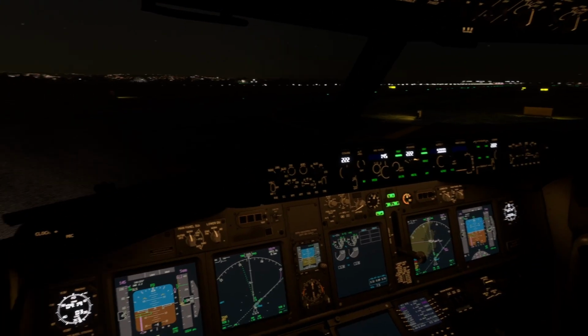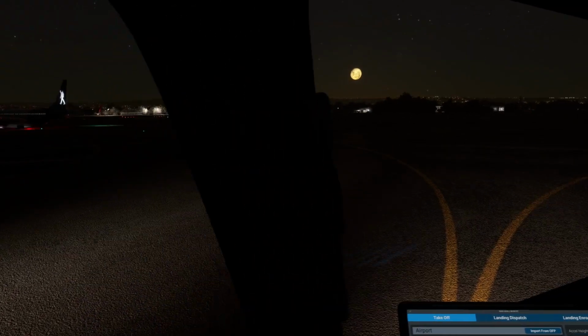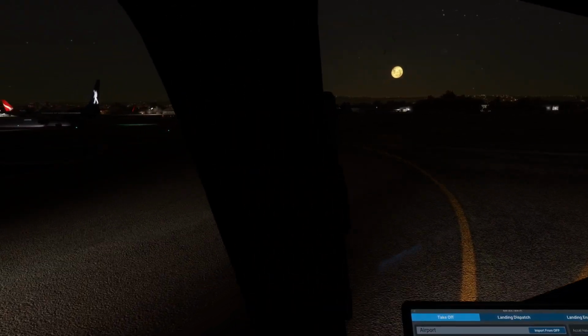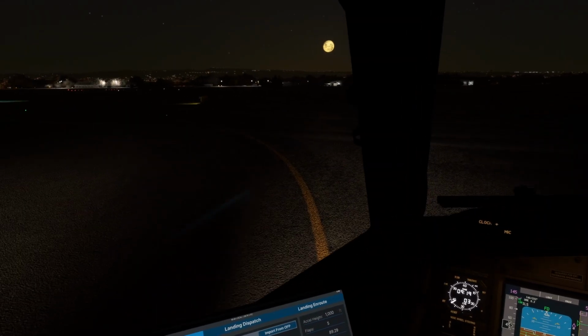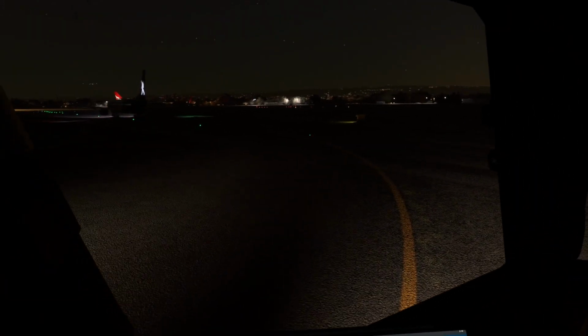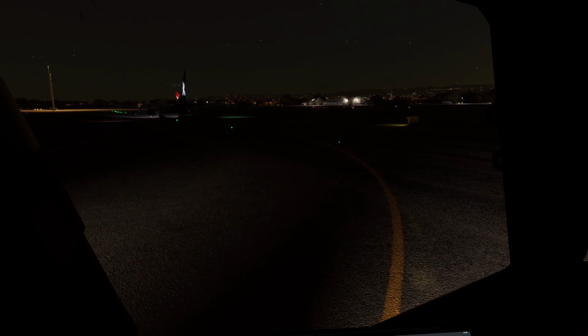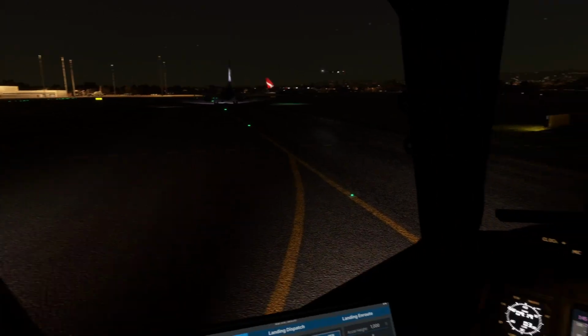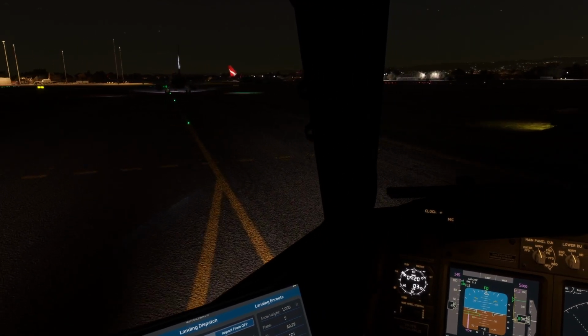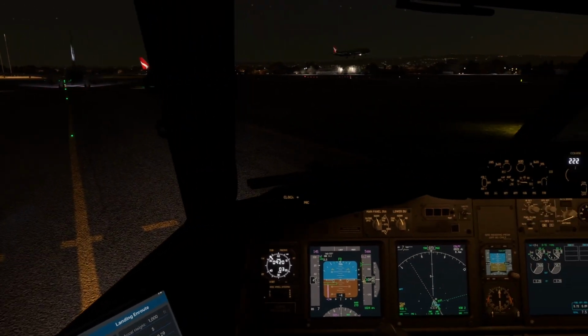And real-world procedures, air traffic flows, operations, right? I've flown into busy events in both Infinite Flight and VATSIM, and it's just different. When it's done all over voice, you hear the different accents, you have to reference charts. It's a high workload situation on landing and rollout. You've got to contact ground expeditiously, dial in the frequency, and read the taxiway signage. Taxi this, give way to the company traffic, and so on.